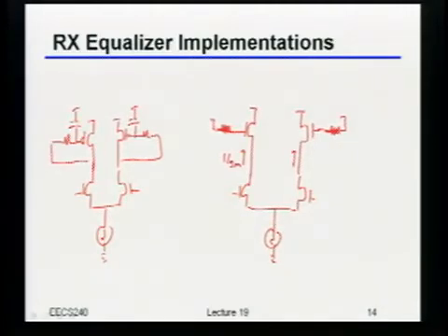You will filter off the gate voltage, so the amount of current which goes in is much lesser. You're right, but physically, what's the element that I'm missing to draw here to show why the impedance actually goes up? Yeah, so there's always a CGS, right? There's always a capacitor from the source up to the gate.